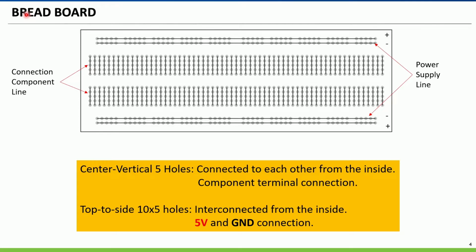And this one is a breadboard. In this experiment, we will use this breadboard when we want to place a circuit, and this one is the connection in the breadboard. You place electrical components in the center, with connections like this. The pins in a vertical line are connected like this.